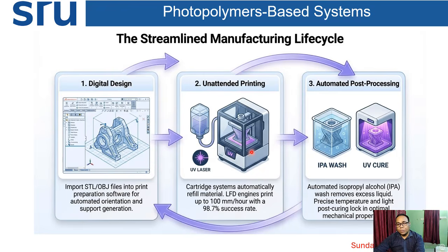Once slicing is done, the complete slice information will be saved after the slicing operation, and that information will be given to the machine. Once the machine receives the complete detail about each layer, meaning how our printing head will be moving in the x direction, how the printing head will be moving in the y direction, and similarly our build platform moving in the z direction. So what the layer height thickness is, complete information will be given in the slicing operation, and it will be saved with the G code, M code, and X coordinate, Y coordinate, and Z coordinate. Complete detail for each layer will be there, and that will be sent to the machine itself.